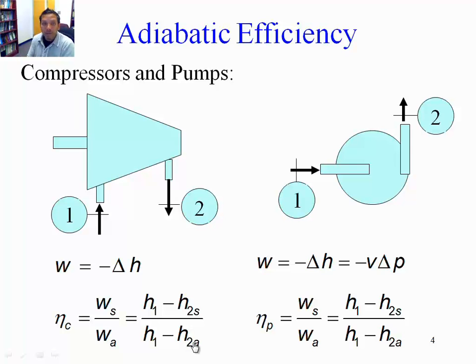The purpose of an efficiency, or the definition of an efficiency, is a number between 0 and 1. So is the efficiency of a full cycle. It is always a number between 0 and 1. It can never be more than 100%, at least in power cycles. Now, for the case of turbines and compressors, obviously it is defined as a number that is always less than 1, less than 100%. You cannot produce more work than the ideal amount of work in the case of turbines. And in the case of compressors, you can never require less work than what is required ideally.